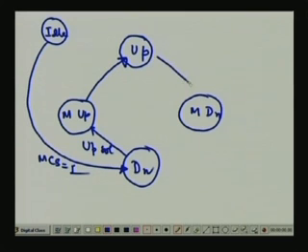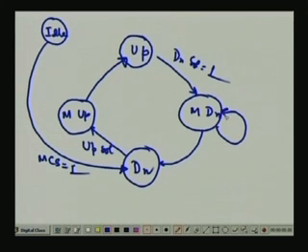In the up state, if you give a down solenoid equal to 1 input, then it will be in the moving down state, and then by itself it will come to the down state. In between, sometimes there are self loops, because it might take quite some time for it to come down from up to down state.